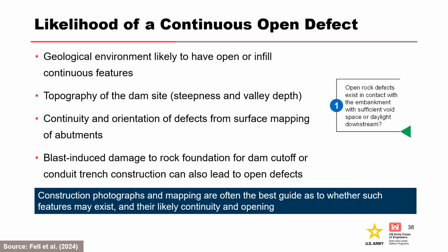Is there blast-induced damage to the rock formation for dam cutoff or conduit trench that can also lead to open defects? Construction photographs and mapping are often the best guide as to whether such features may exist and their likely continuity and opening. Don't consider cutoff elements at this point in the event tree. Effectiveness of foundation treatment is a separate node.